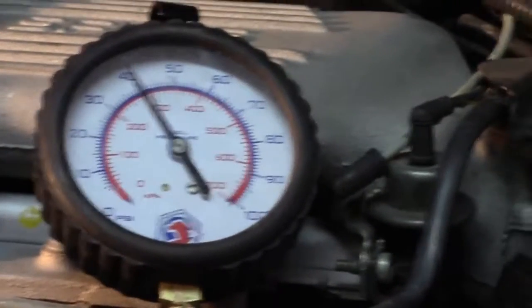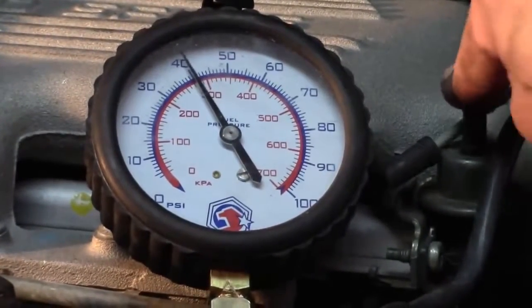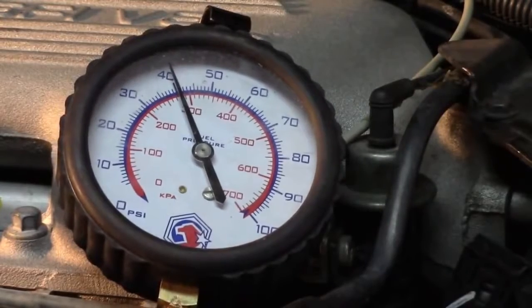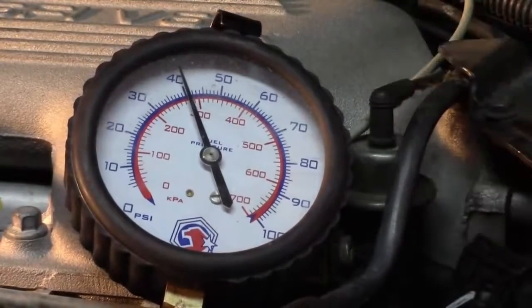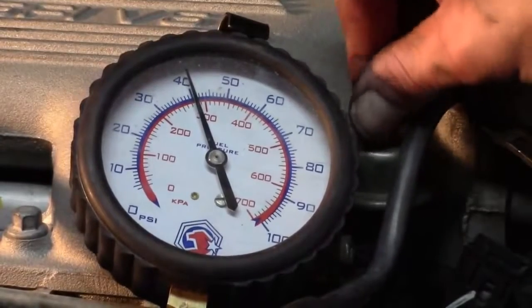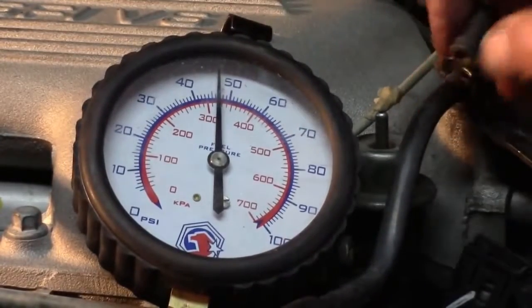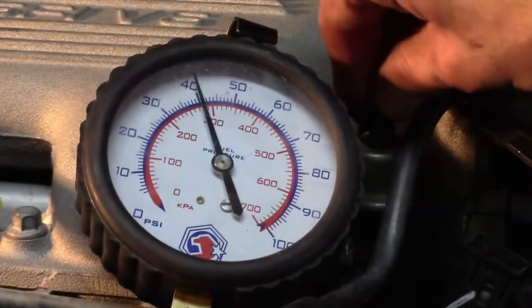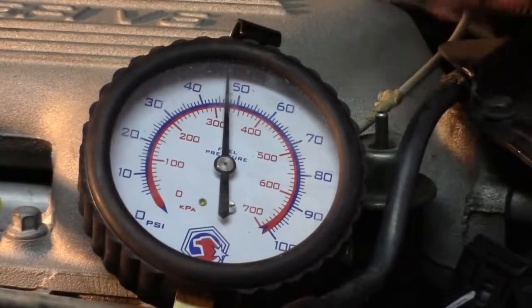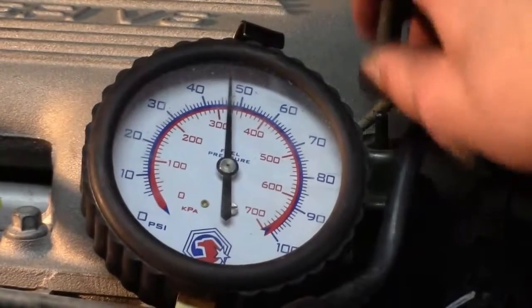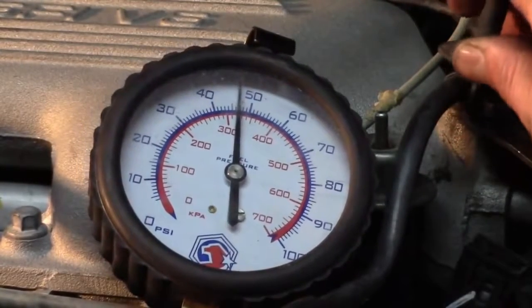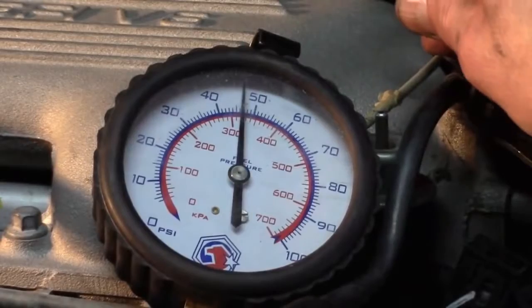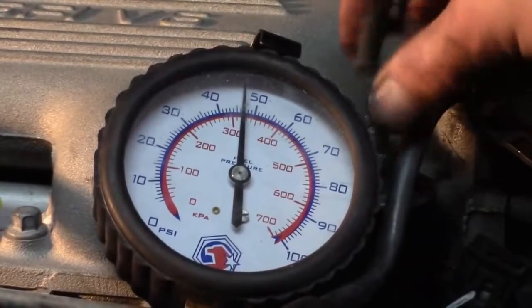Now, what is going to happen when I remove the hose from my fuel pressure regulator? Well, we know what should happen. The regulator is actually open right now because of the engine vacuum through the hose. So we should see a pretty good increase in fuel pressure if I pull this off. And we see we do. It's back to almost the priming pressure. That's why the pressure dropped when we started the engine, because we added vacuum to it. So right now, we also, of course, have a vacuum leak here, so I'm just going to plug that with my thumb right now. But you can see that the increase in pressure is due to the fact that we've removed vacuum, which is the same thing that would happen, as I said, when you would apply throttle.